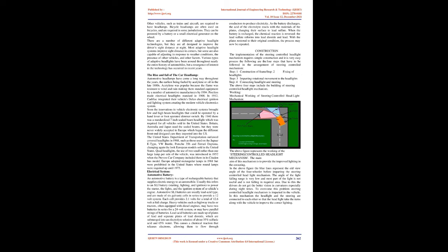To minimize tire wear. Requirements of a good steering system are: the steering mechanism should be very accurate and easy to handle. The effort required to steer should be minimal and must not be tiresome to the driver. The steering mechanism should also provide directional stability. This implies that the vehicle should have a tendency to return to its straight-ahead position after turning.